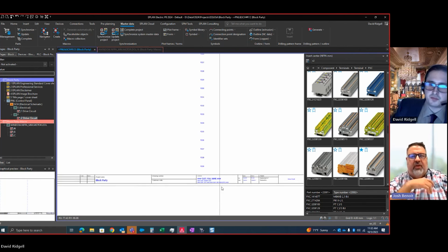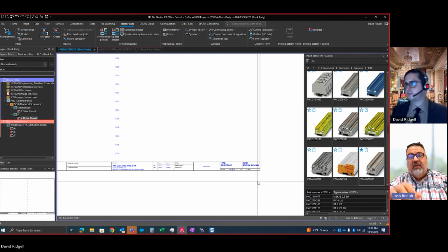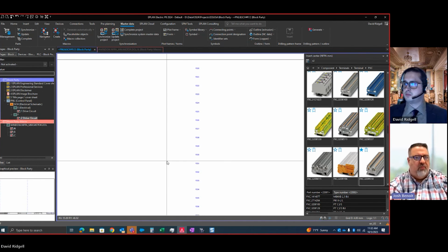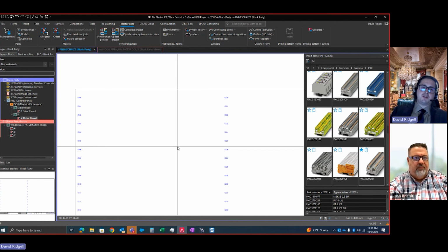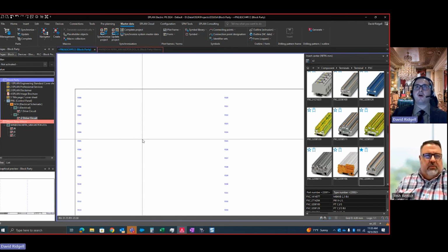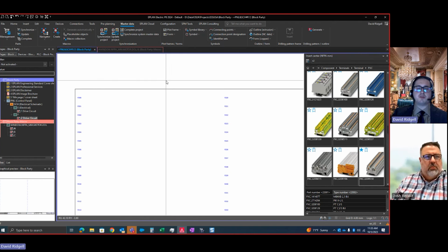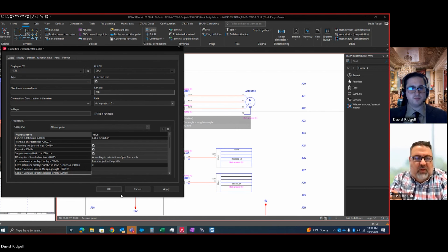Now, you played around with the Platform 2024 calculation function, and I know that in the past, because this is why it was addressed, the voltage drop because of cable length, that was a big problem before, wasn't it? Yes. So that's one of the exercises in our update training. We have an update e-learning, so some people might have access to that. So in the cable, you have a length, right? I could say this is 20 feet.